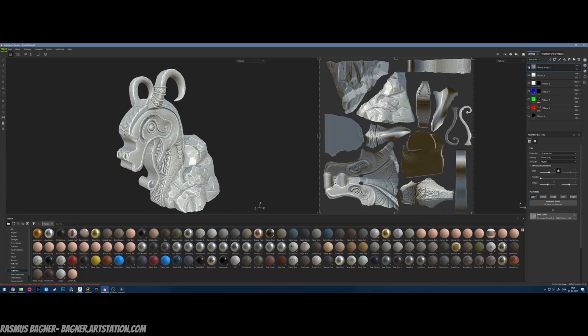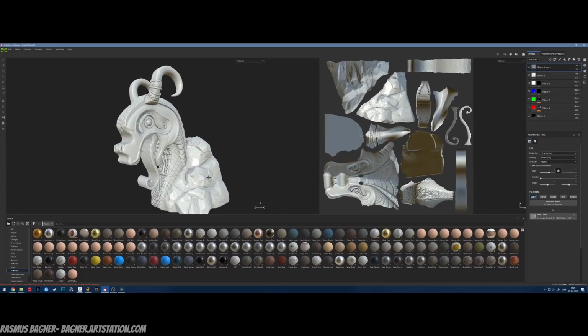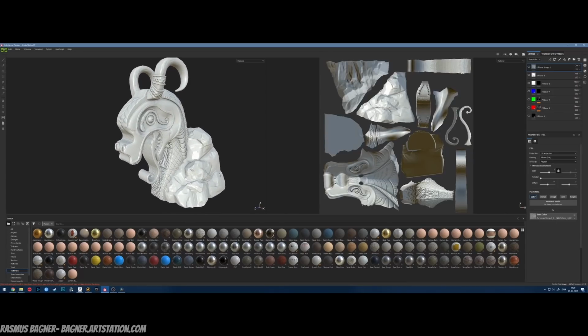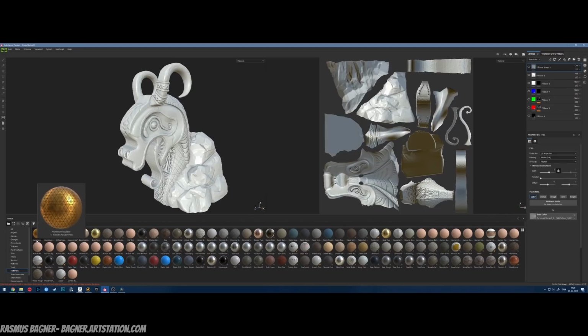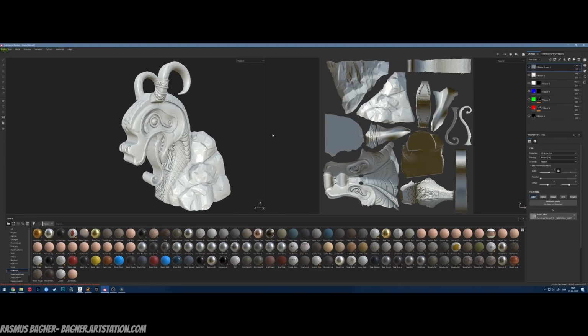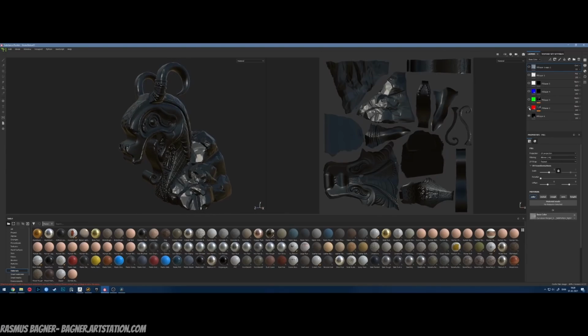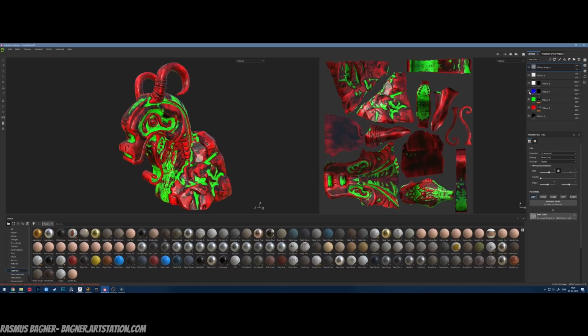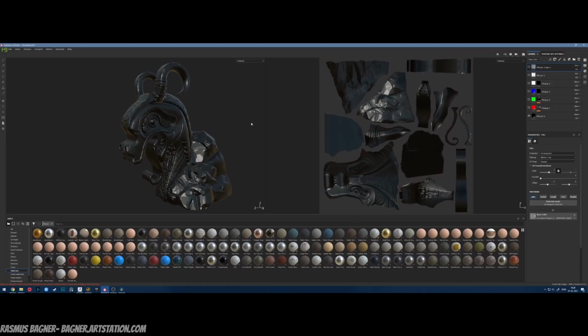When you've baked your curvature, ambient occlusion, normal map, and so on, you are ready to use the masked workflow. So what's the masked workflow? It is essentially just one masked texture. Every texture contains the default value, red channel, green channel, blue channel, and alpha if you want. So by default, everything that is black in the masked texture will be, in my case, one of the rock textures I showed earlier.